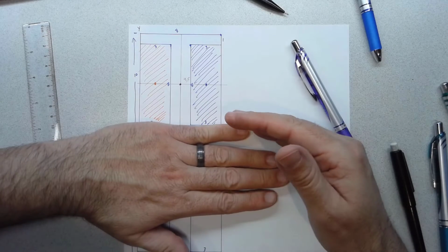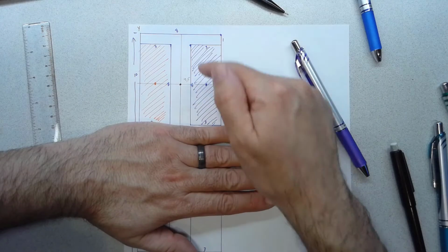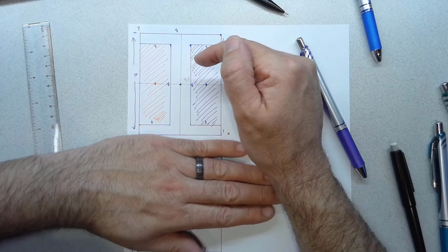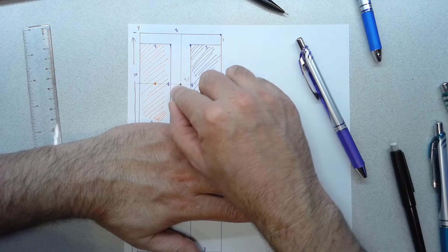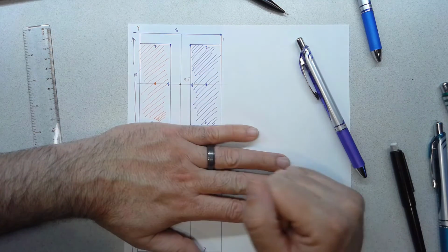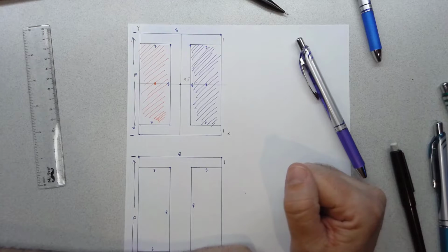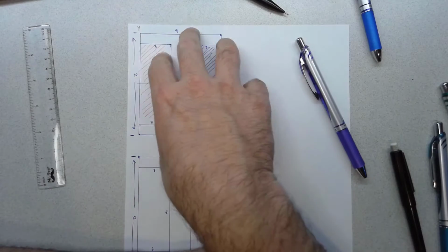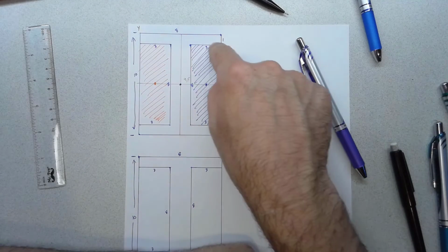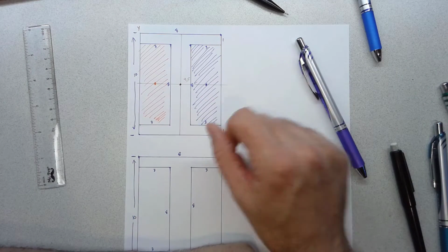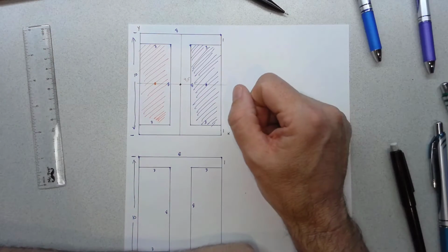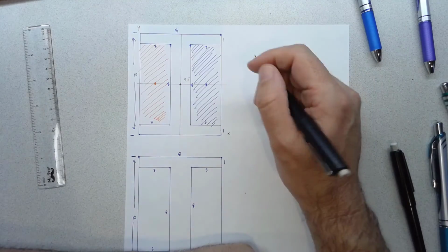Let's say if we look at a T-beam, the centroid of the final shape no longer would be right where the original one was. And that's when we have to move into the parallel axis theorem. So doing it this way, whole rectangle, and then subtracting out two pieces that are still symmetric, is kind of an easy step into finding composite I's. So let's get started.